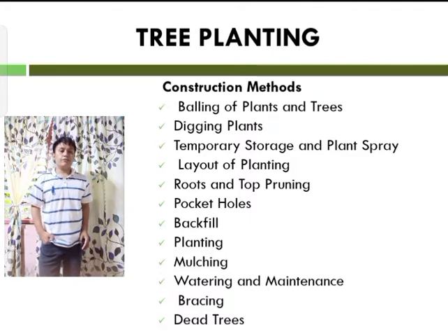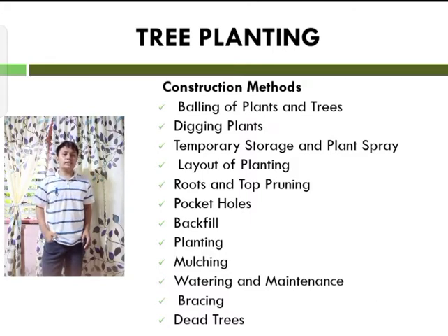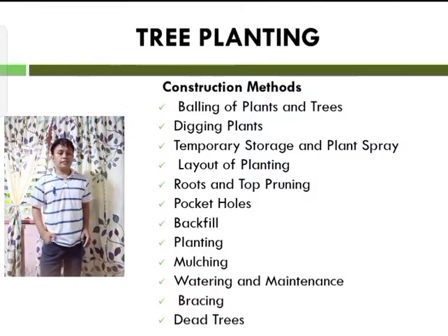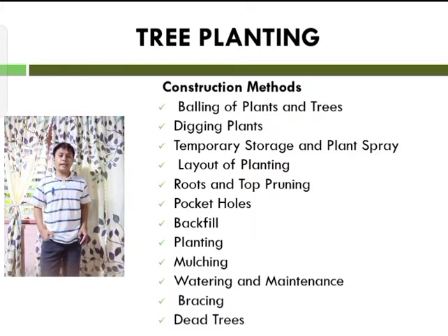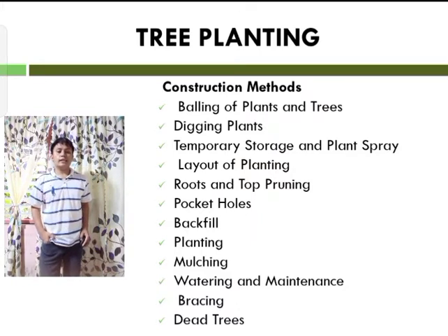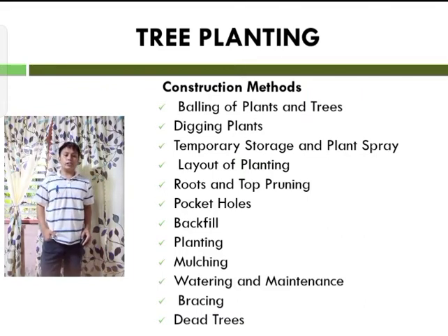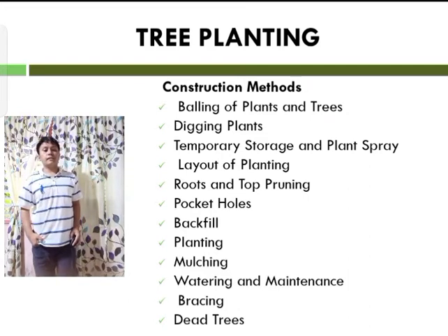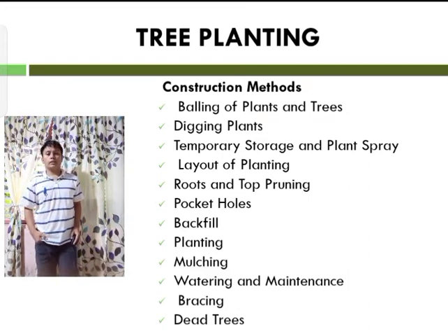Then we have plantings. The plants to be planted shall be of the species, variety, and size specified. The operation of actual planting shall not be performed at any time when the soil is not in a friable or workable condition. The engineer shall also approve the location of each individual plant, taking into consideration its size and shape, in order that the best possible arrangement will result.